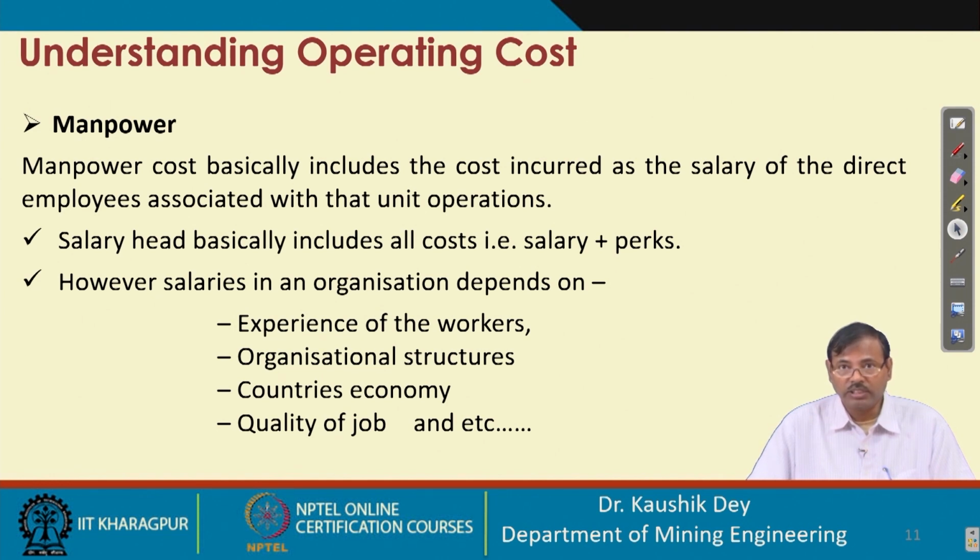In sandstone etcetera, where silica mass is there, that means angular grains are there, the consumption of the bit is very high, because of the high abrasivity of the rock. So, those parts must be considered when the planning is carried out.